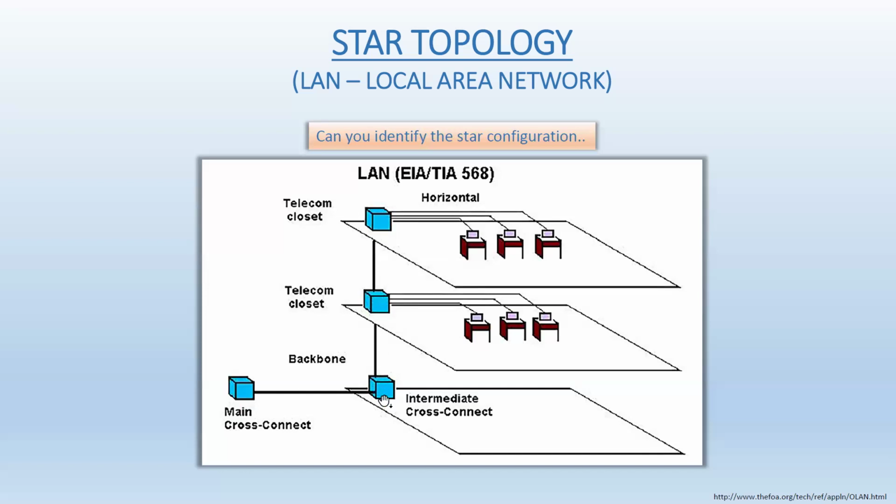This concept can take different shapes and forms. For example, if there is a huge shopping mall, you're going to have one big room where everything comes in, and from there you're going to have secondary demarcation points that feed certain areas of the mall. So let's say this could be the main demarc point, and it could feed a second demarcation point that feeds the east part of the mall.